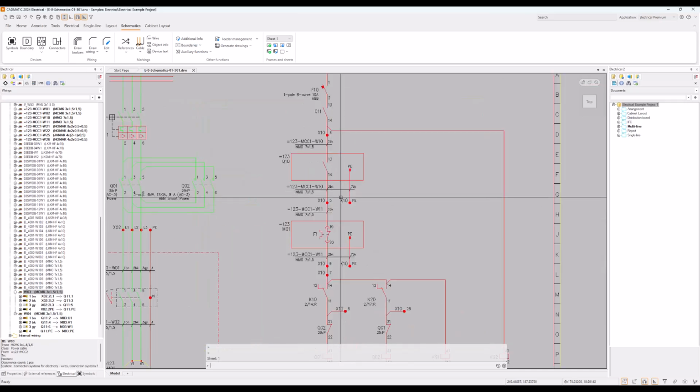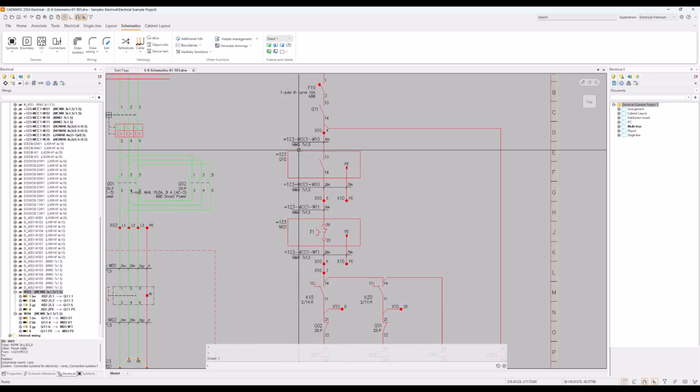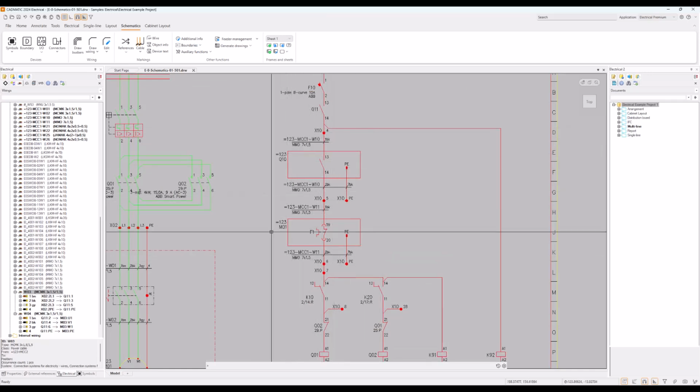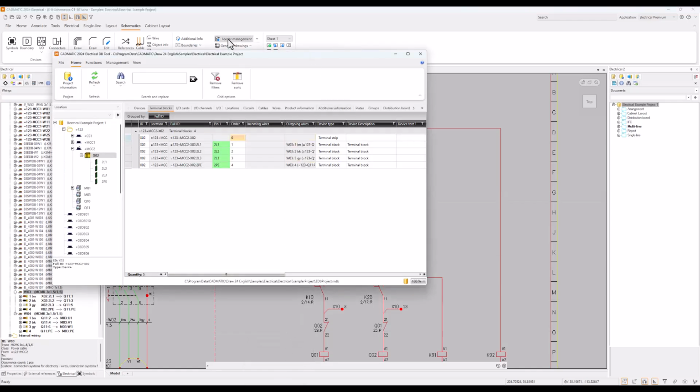So let's say we want to change these MMO cables. In the first sheet, we have the Whiskey 10 and Whiskey 11. These cable types, we want to change them from 7 times 1.5 to 7 times 2.5. And how to do that is to, again, open your database tool. First you will go to management, and we need to manage some cable types because I happen to know that we don't have any MMO 7 times 2.5 available.